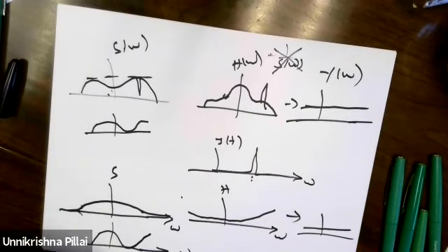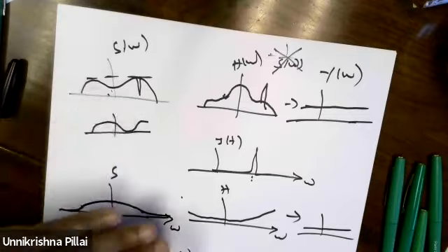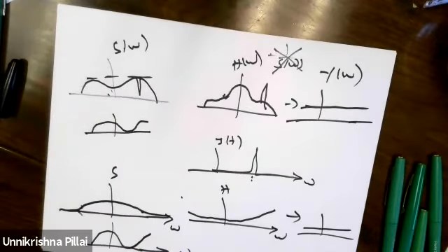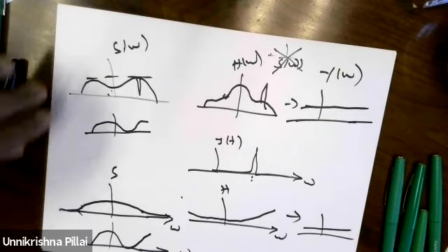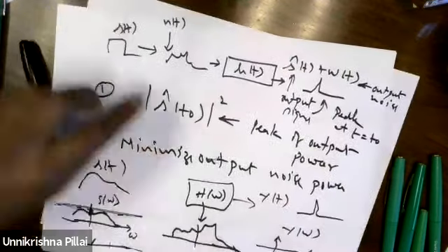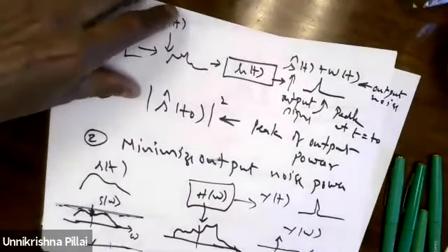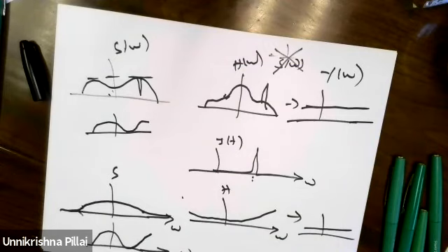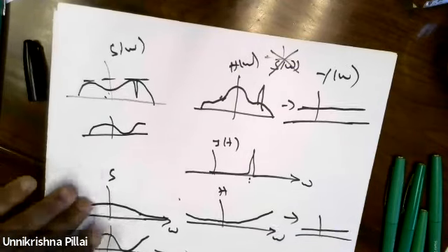But depending on the problem, you may be able to see, this is where the noise will help. If you have noise here, noise will increase the floor, and there will be no zeros, and then you can work on it, right? So that's always an idea. And remember, we went through this in a sense. I gave you the spectral factorization and whitening, right? So the whitening approach, except that this problem is for a deterministic problem. Simple thing, nothing stochastic here, just a signal. A signal is coming in, I want to compress it. What is the filter to use? A simple problem. But I'm saying now you have enough ideas to work on that too.